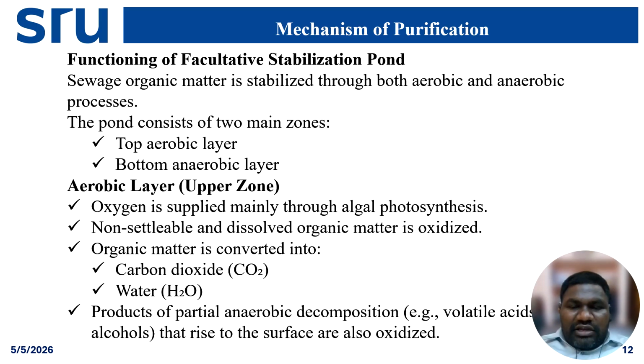So what is the mechanism of purification? How does it happen and how can it remove the BOD? First of all, the functioning of a facultative stabilization pond. Here, organic matter is stabilized through both aerobic and anaerobic conditions. So the entire zone we are dividing into two zones. The top one will be the aerobic layer, and the bottom will be considered as the anaerobic layer.